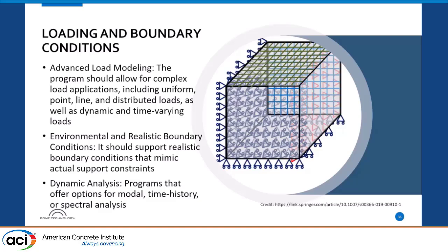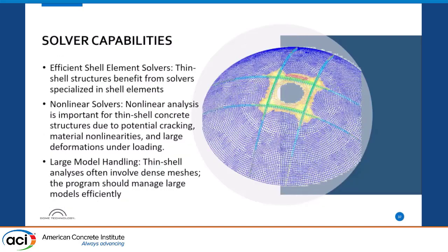time-based or directional. And sometimes you want to do some long-term analysis, some dynamic analysis for seismic, or to see the effects of creep on the structure as you're looking at stability. You want to make sure that your solver is efficient at solving shell elements, and that it can handle any nonlinearities that you're going to take into account, whether that's a true nonlinear analysis or not.